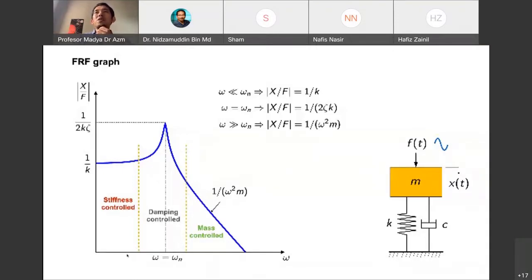If the speed of the machine is lower than the natural frequency of the machine. So that can be two different things. Natural frequency is determined by the mass and stiffness of the mounting, or the flexibility of the structure. But what excites the vibration of the machine can be any frequency, which in the case of a rotating machine is usually the speed of the machine.